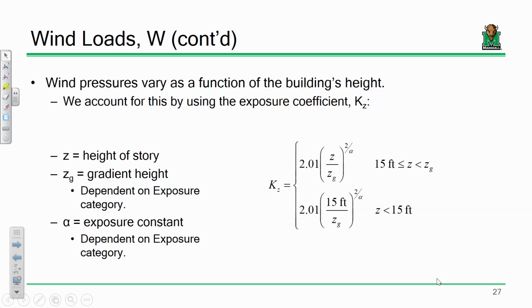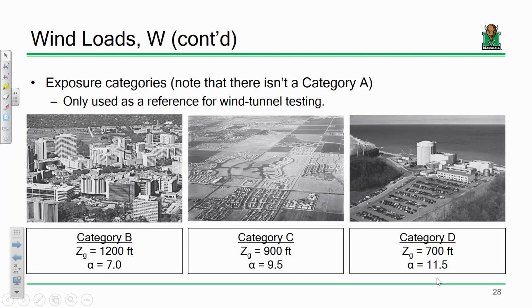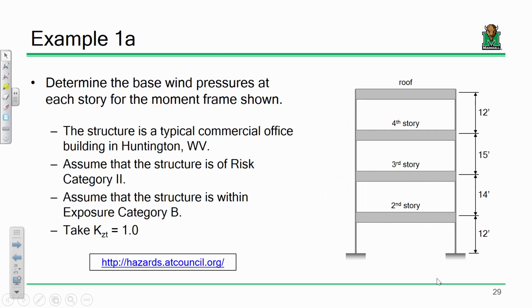Like I said, the real big constant is the KZ value, and the example that we did last time was really focused on making sure that everybody understood how to compute KZ. I mean, everything else was pretty straightforward. Just look up the wind speed, choose the appropriate constants, and you were good. So, did anybody have any questions about example 1A?